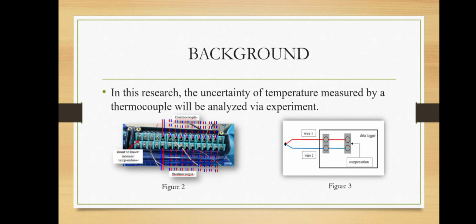As what I have mentioned just now, previous way is complicated. So, the RJC error has been determined by measuring the terminal temperature and the internal temperature for each channel as shown in Figure 2. It takes time and effort to obtain this temperature of all channels. To obtain the uncertainty of the reference junction compensation, this measurement needs to be repeated many times. Therefore, an easier and faster way to obtain the reference junction compensation error is strongly required.